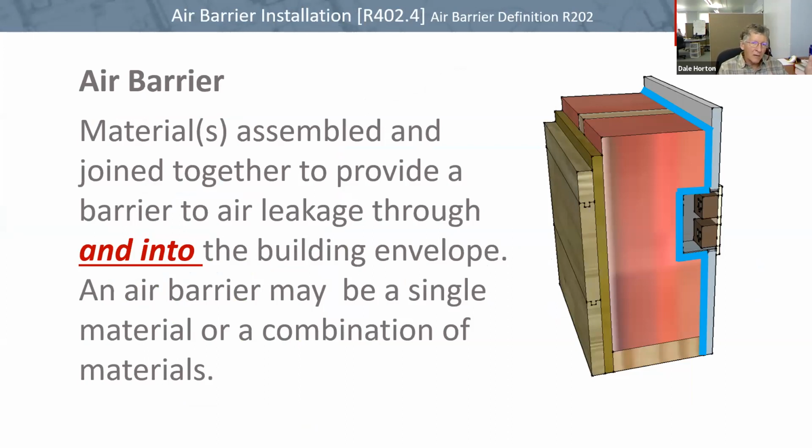We've talked about vapor retarders. Vapor retarders are to prevent movement of water vapor into the wall through diffusion. And with an air barrier, it's preventing the movement of air and water vapor into the wall via air transport. Montana amended the definition of an air barrier, and I'm not sure if this definition will be amended. I think I proposed a slightly different version that I think is a little clearer in terms of its intent. Whether that's going to be accepted, I have no idea.